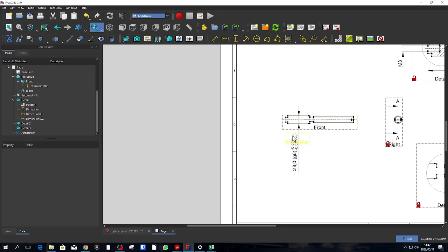Basically what the envelope principle means is that when the component is at its maximum material condition, it has to have perfect form. If you don't add the envelope principle, you will have to specify the cylindricity or the straightness of this part of the shaft.